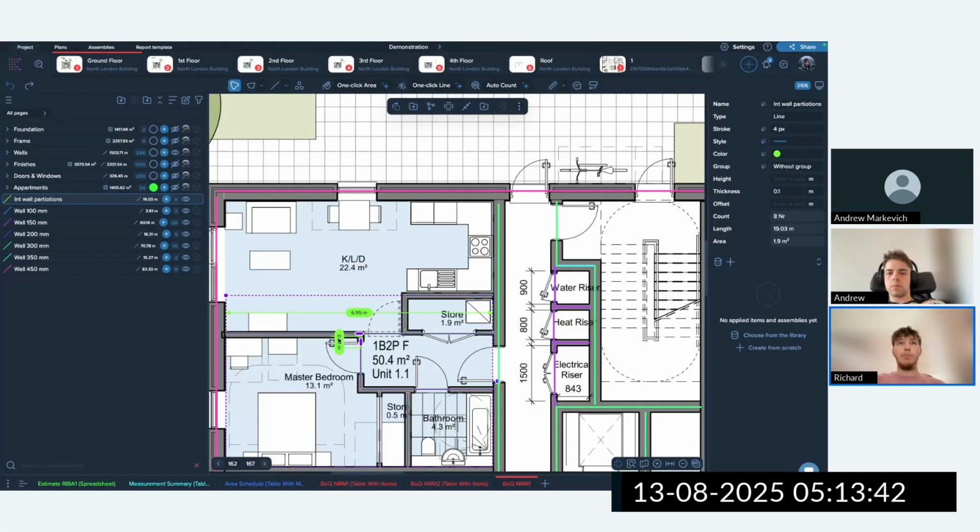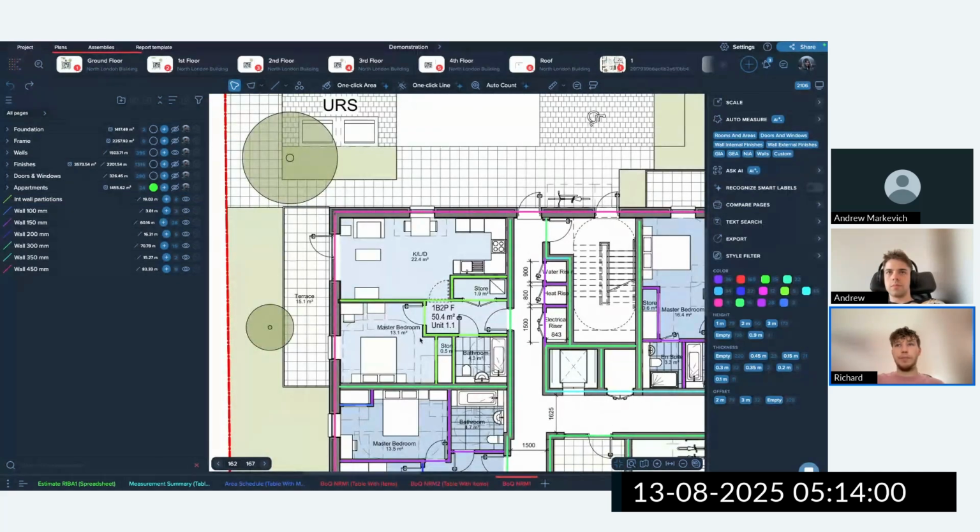If I want to input their height, I go here and say height as 3 meters. So now I get additional quantities. You see, I have by default count and length, but at the same time, you can get bottom area, vertical area, and volume as some additional measurements.